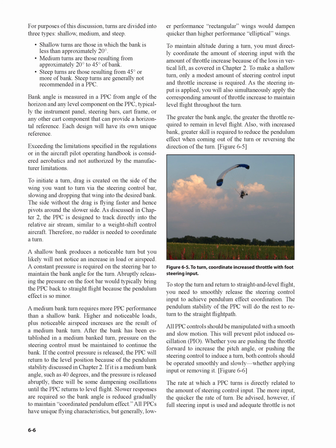Slower responses are required so the bank angle is reduced gradually to maintain coordinated pendulum effect. All PPCs have unique flying characteristics, but generally, lower performance rectangular wings would dampen quicker than higher performance elliptical wings. To maintain altitude during a turn, you must directly coordinate the amount of steering input with the amount of throttle increase because of the loss in vertical lift, as covered in Chapter 2.